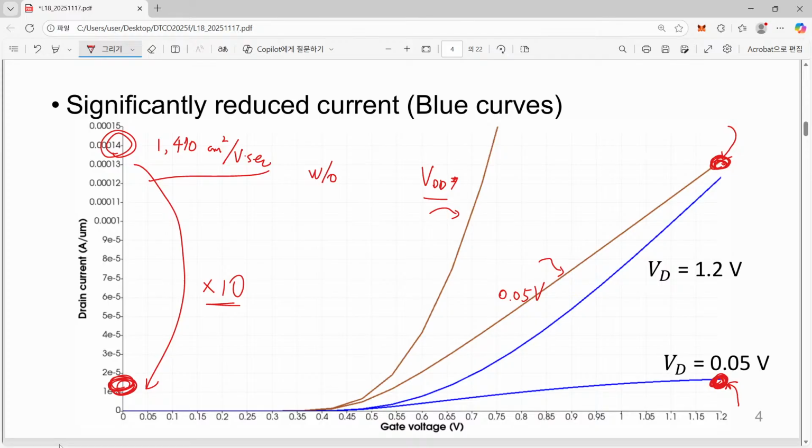However, it is never achievable in practice, because in our case we have doped quite a lot, and also our electron channel is quite close to the rough surface between silicon and silicon dioxide, so we cannot expect such a high mobility value. So in reality, if we have values like 200, I will be very happy with this number.